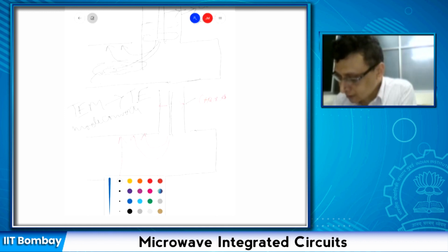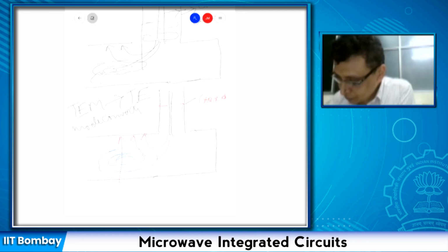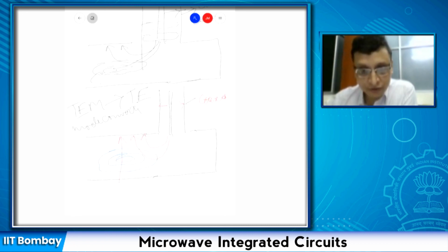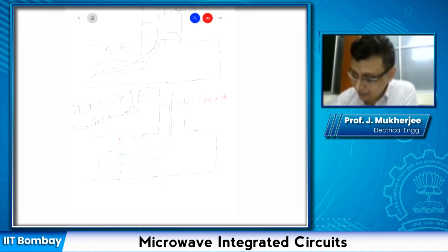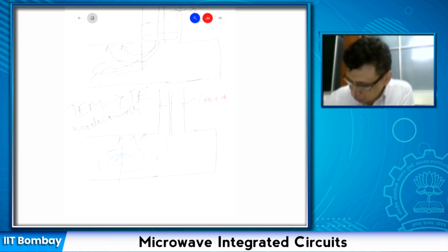Now what mode is this? The figure is TE. You are making electric lines vertical. Okay, fine. So you see, that's what I was talking about, the engineering. Because I connected my coaxial cable this way, I could convert my TEM wave in the coaxial cable to TE. Now, if you want to transmit mostly through TM, then you'll have to think about how to convert this TEM to TM.